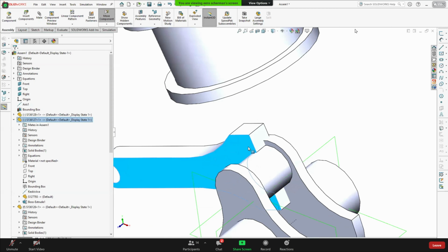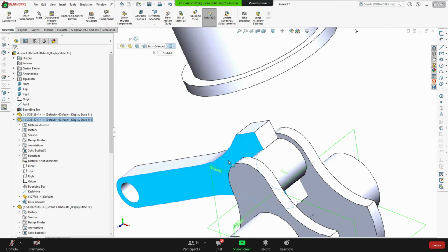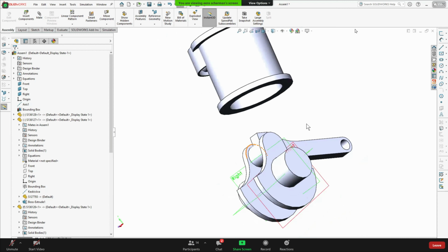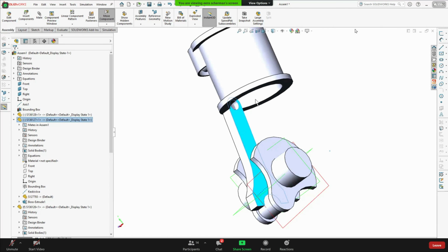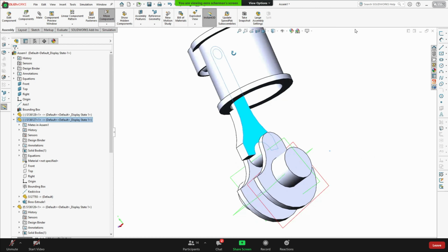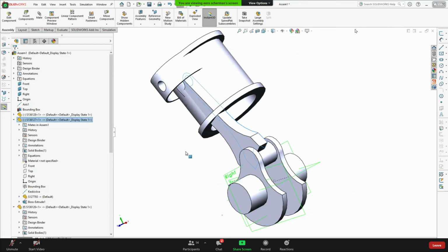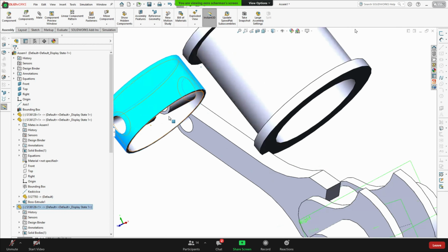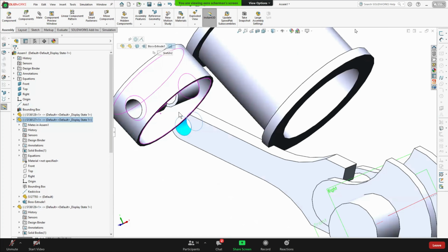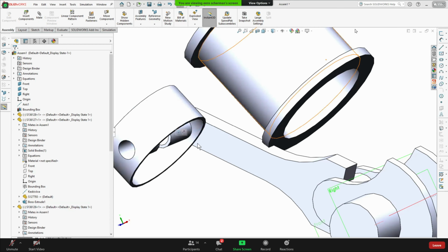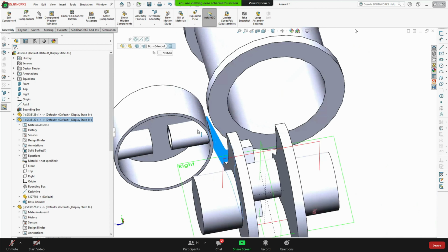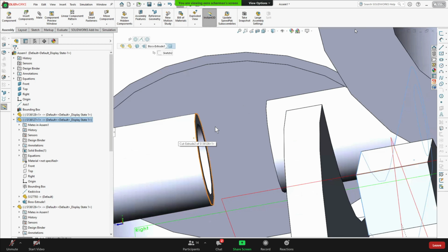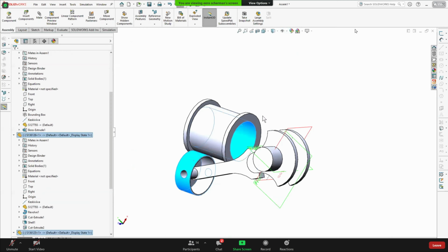Let's make, for example, this face surface coincident with that one. Now it's always staying on that one. And finally, I must put the cylinder piston on the other end of my connection rod. Firstly, it must be located here, the pin must be like there, and this face should be coincident with that face. Now, if I put the cylinder piston into the cylinder,